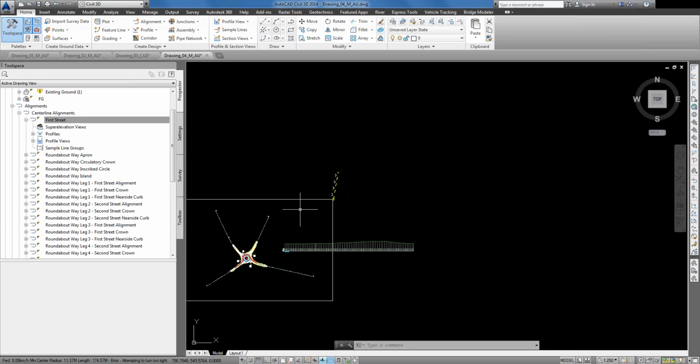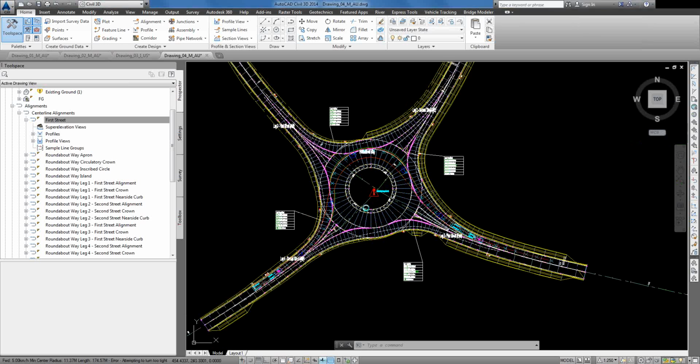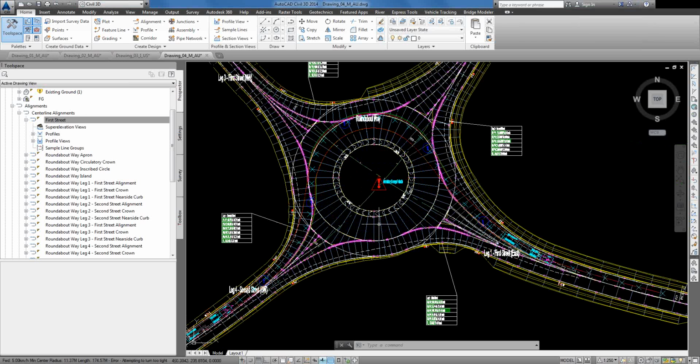So just to summarise, when you go to model a roundabout, obviously you need to place your centre lines first, then apply your vertical, so do your horizontal geometry, then your vertical geometry. Then once you've done that, you can go through, run the tool, and then the program will go through and pick up that information from those profiles and amend those appropriately.